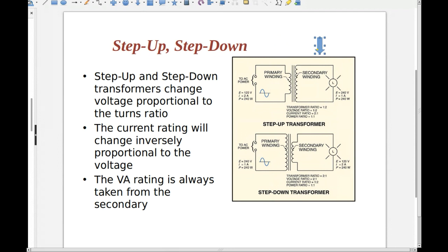So those transmission lines outside your house are only running at maybe 7,000 to 10,000 volts. But those great big transmission lines are carrying voltages way up, some of them around 500,000 volts. So they have these substations that break it down from the really, really high voltages down into just high voltages that are run out to the local communities.